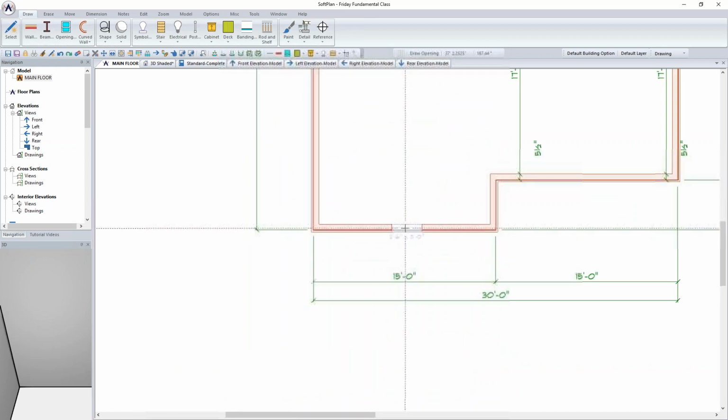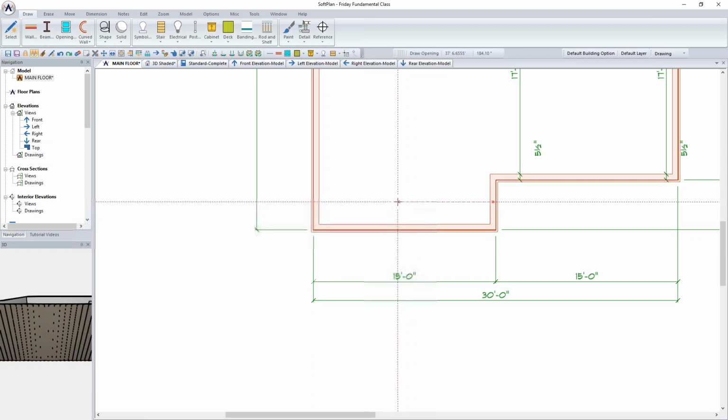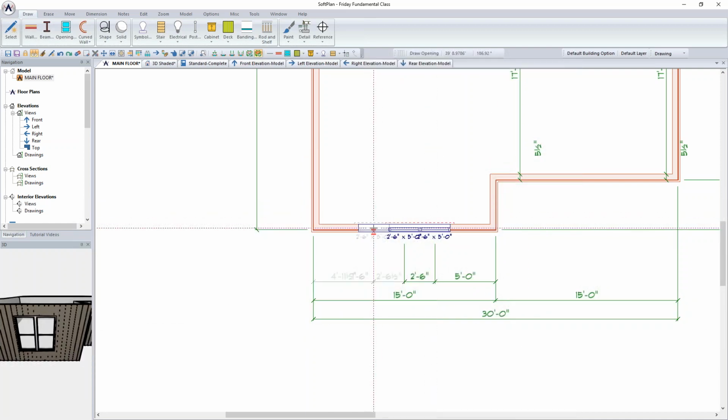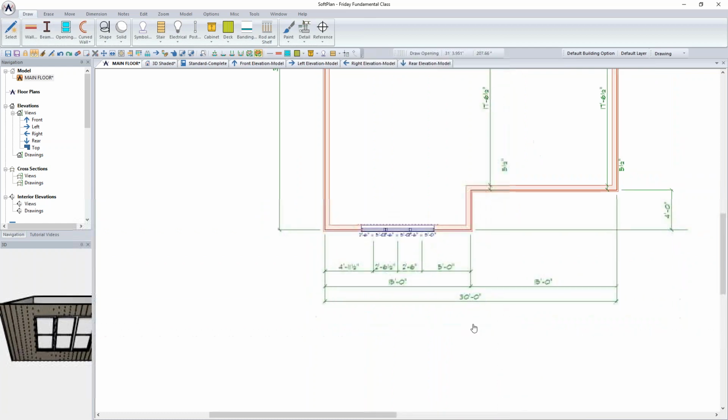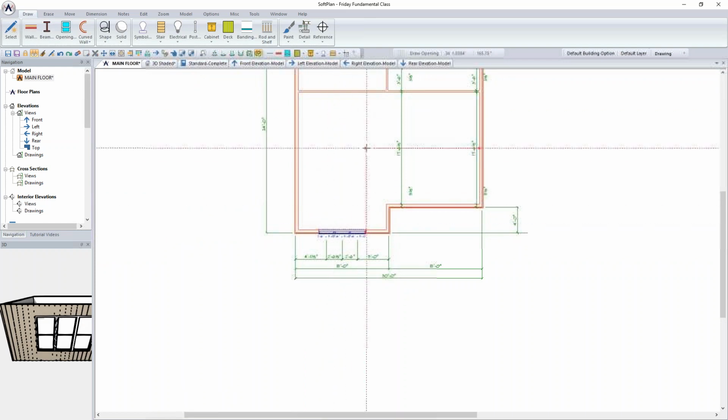I'll click OK on this, and I'm going to position my cursor, turning on the F11 snap feature. I'm just simply looking to snap this into the middle. Now, snap is located also in the toolbar, so you can pick that up there. Okay, and I'm going to turn my auto dimension feature on so that as I draw this, it's going to now begin to pull my dimensions off. Okay, and again, I'm going to add a secondary opening beside it, and then another one here. All right, so we now have three, if you will, openings, and they're mulled across the front here on our